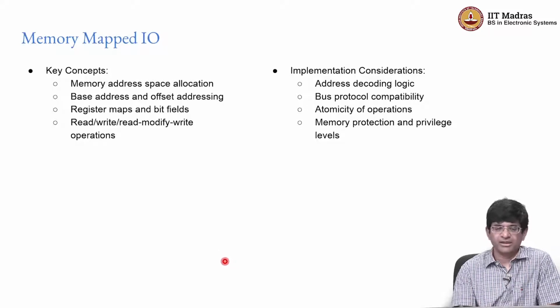Now, as mentioned earlier, there are so-called direct IO instructions in certain kinds of processors, but these are not very common. The memory mapped interface is a more generic version and in a lot of ways a better abstraction than having separate instructions for IO. Although it may be that for some specific kinds of applications you might find that having a separate set of instructions whose only job is to communicate with IO peripherals may also be useful, right.